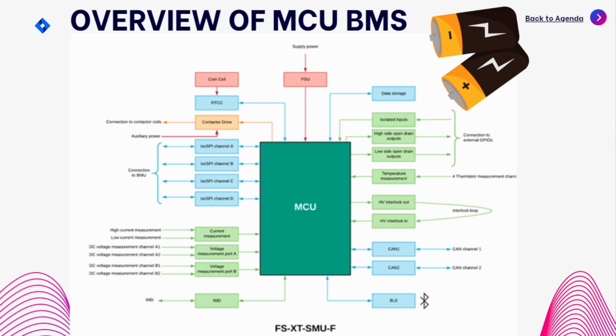For cell safety, the MCU has the following functionality also. Prevent any cell from going into an overvoltage situation inside the battery pack. This is achieved by giving a turn off signal to the contactor. Next, prevent the temperature of any cell from exceeding the upper threshold limit by reducing or stopping the current or activating the cooling system in the battery.